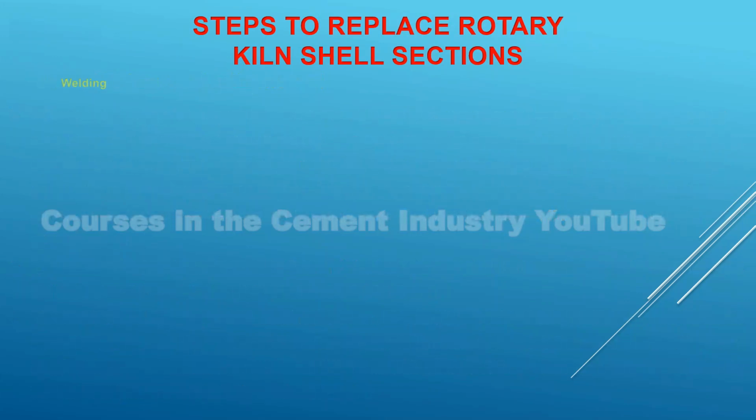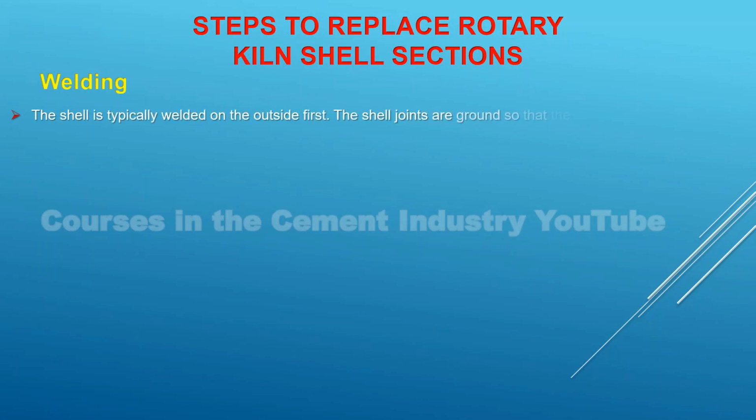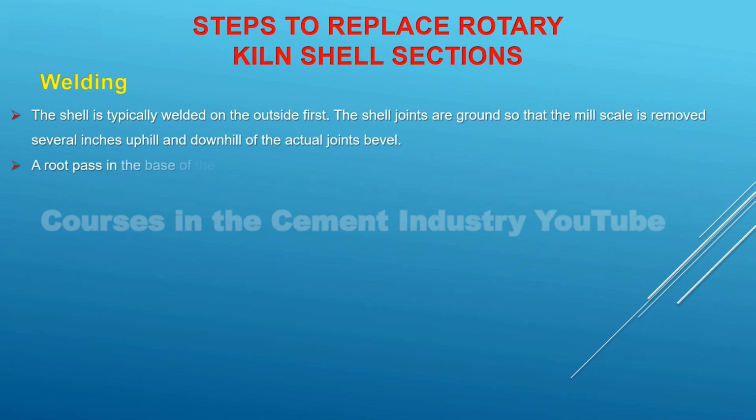4. Welding. The shell is typically welded on the outside first. The shell joints are ground so that the mill scale is removed several inches uphill and downhill of the actual joint's bevel. A root pass in the base of the bevels is welded in by hand, with the welder taking care to properly preheat the shell.